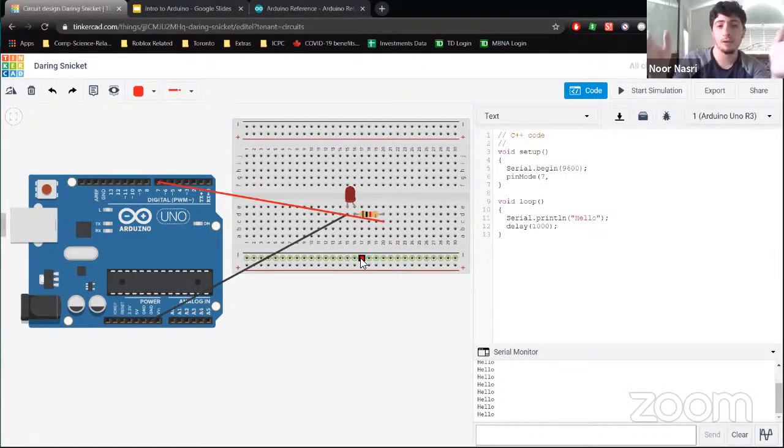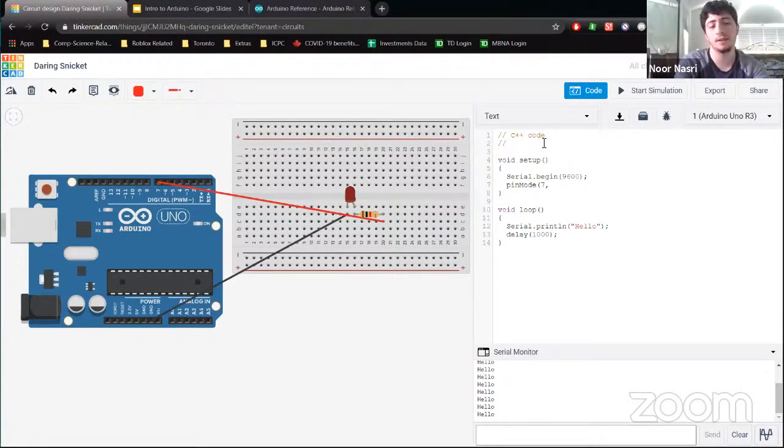Now, for those of you that have taken programming before, you'll know that you don't really want to put these numbers in. You want to make them variables, and then you can change them at the top and everything changes right away. For those of you that haven't, that's okay. I'm just going to write int, which tells me integer, so that's going to tell me the type the variable is. And I'm going to put pin is equal to 7. It's just as it sounds, at the top, before anything happens, I'm telling the program this is what this word means. It means 7, so when I put pin, it knows this is 7. And then I'm going to go to the next one and write in that it is output. You can either tell it it's input or you can tell it it's output.